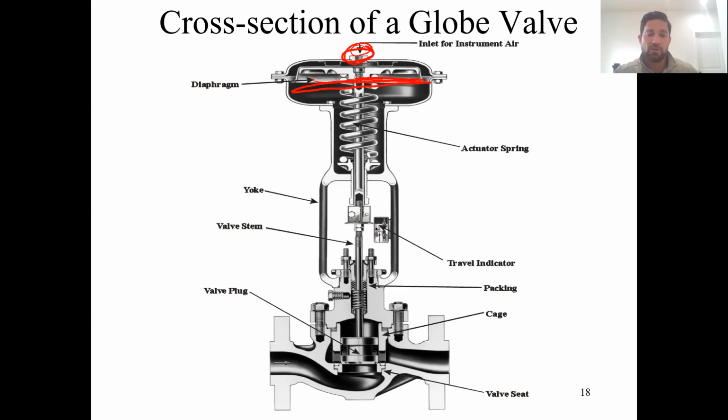One thing I want to note, especially for a valve system, is that some of the driving force for this system is going to be the spring. So these control valves are typically going to be governed by what's called a first order differential equation. The rate at which the flow changes is going to be first order, because the response is typically governed by the performance of the spring. If we look down here at the bottom, you can see that we have the valve stem, or the plug and the stem, and then the valve body.